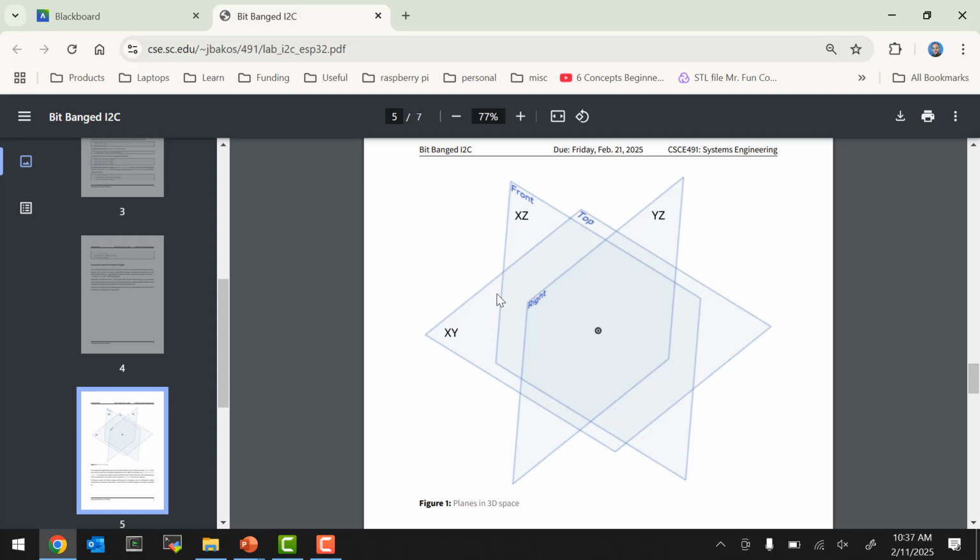And then there's also an I2C decoder built into the oscilloscopes, which you can use if you don't want to read binary data. If you want to see if the scope can interpret what's going on, that's also available. You just have to set up the decoder. You can also use the digital probes. That's easier because you can just plug those straight into the header instead of having to clip onto the sides.